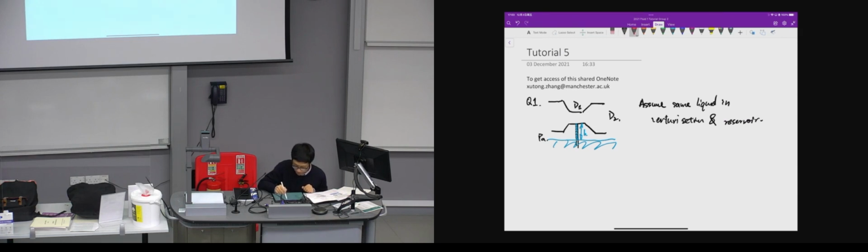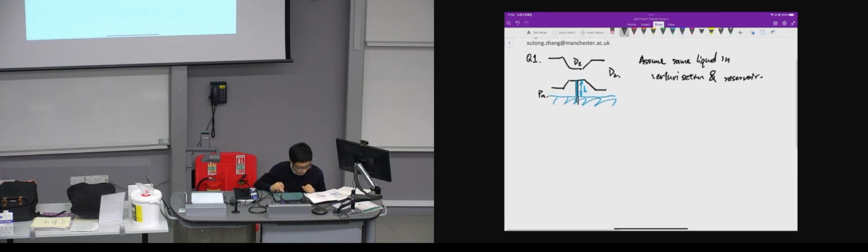From the problem, the first thing we need to think about is that it says explicitly to use the Bernoulli equation. So we need to first check if we can use Bernoulli in this scenario. This flow is steady, incompressible, and inviscid. So we can use Bernoulli's equation.